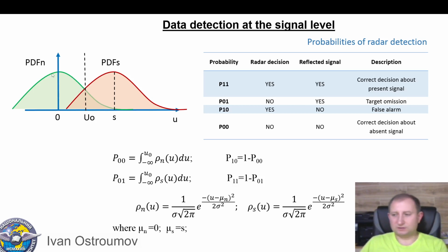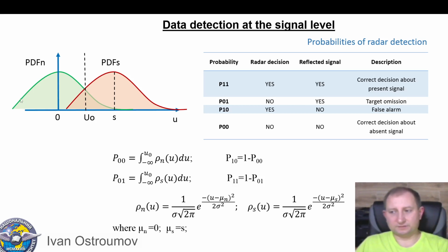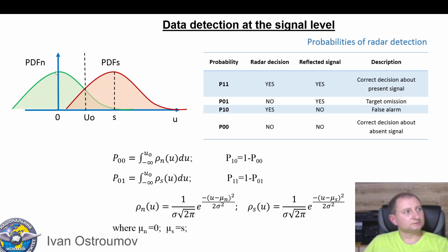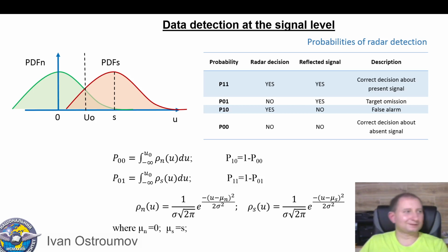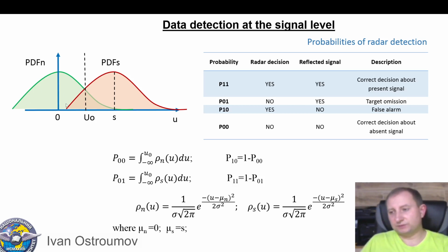It means that the more frequently in the channel, noise will be close to 0, and more valuable fluctuations of voltage will be much more rare than quite small events near 0. The probability function shows us probability, and the probability density function is the same, however it was scaled to get the area under the probability density function equal to 1.